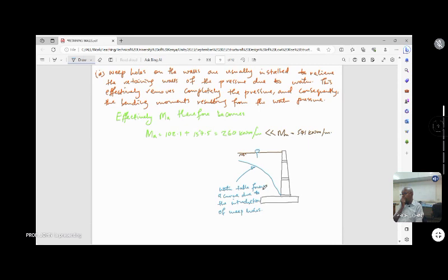This curve is similar to what they call the pumping curve of a well. You know, when you dig a well, you're pumping out. The water table is not a perfect linear cone; it does a curve in towards the well. So as you're pumping, the water table around the well does a curve like this. That is a cone, but it is curved. You see, it's the same concept.